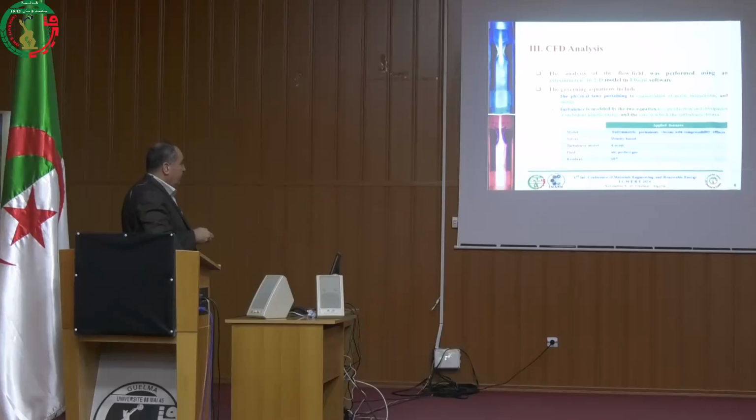Using Fluent software, we have told the computer program that we'll be using the 3 conservation equations: the conservation of mass, the continuity equation; the conservation of momentum, the Navier-Stokes equations; and the conservation of energy, which comes from the first law of thermodynamics. If we take these 3 conservation equations, we cannot close the system; it is open, so we have to close it. We have to add 2 other equations, and they come from the turbulence.